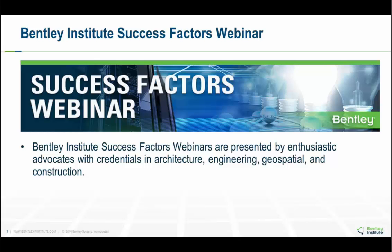As an alternative, you can also say this is a dog bone, but not go to the effort of modeling the dog bone explicitly. At the end, to account for the additional sway that you would get, you can just multiply your drifts by, say, 15%, which is, I believe, the commonly accepted approach. So you have the options. But in short, yes, the effects of P delta are included in the effects of the reduced stiffness in the dog bone. That analysis takes into account all of those effects working simultaneously.